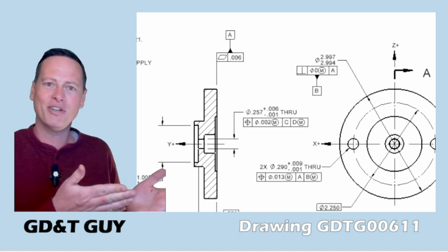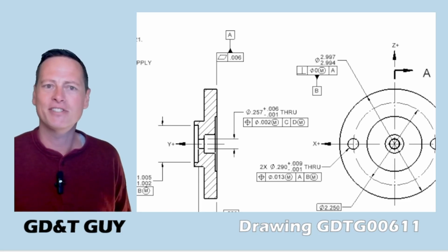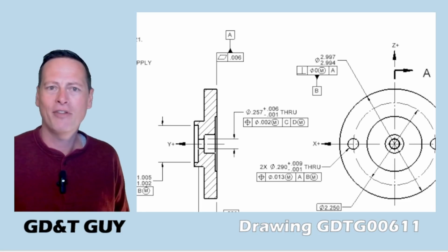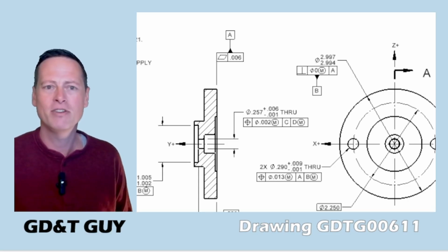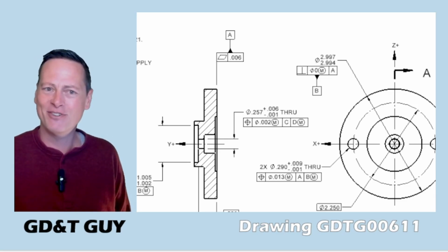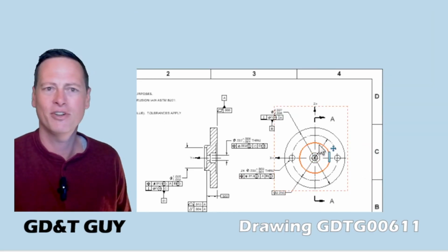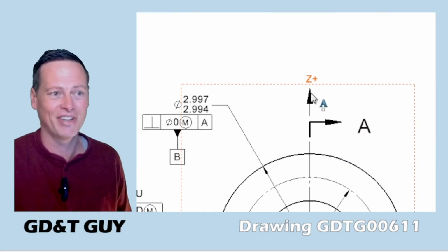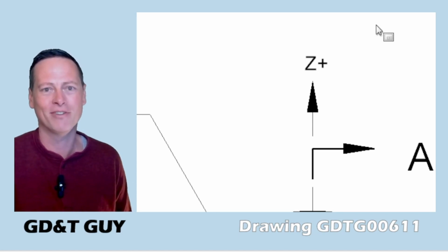That's not really what I'm trying to do here, but I could see how this could help an inspector, especially using a CMM, trying to map out the inspected positions of hole axes in XYZ. In that sense, I like it, but I'm not sure I've ever seen these arrows on a real drawing. I can even see them causing confusion for someone who's never seen them before. Also, I only really know SolidWorks and NX, but I've never seen this as a canned function in a CAD software, and I would be really surprised if anyone provides it.